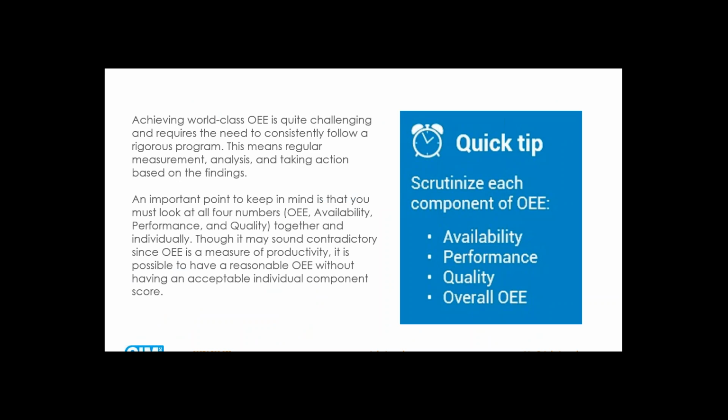So what I would suggest is aspiring to world-class OEE is all great, is all well and good, but you need to set yourselves appropriate targets that will obviously challenge yourselves and your workforce, your operations team and your engineers, but targets that they can actually achieve. It may be that due to the profile of work, the profile of production orders that you receive, that you need to perform multiple changeovers in a day or in a week, at which point your ability to achieve 85% will be slowly degraded over time.